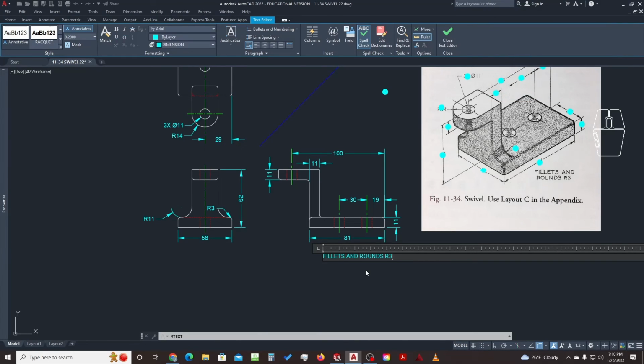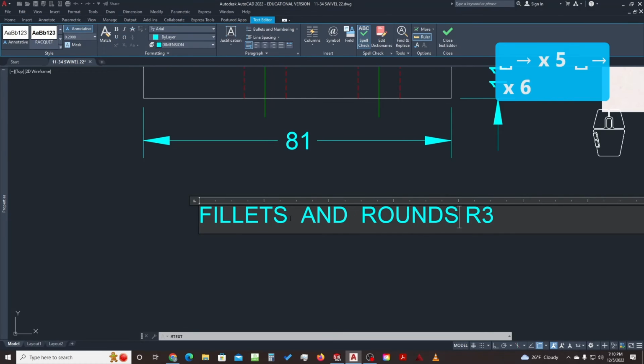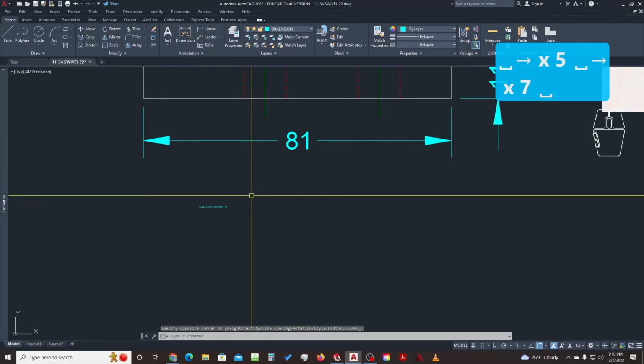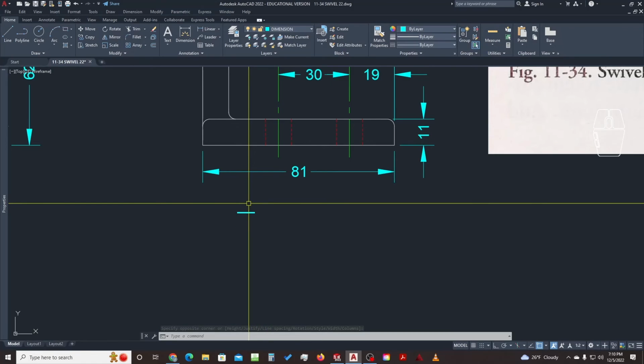And when you are using caps lock, this is not 100% mandatory, but it is very good practice to add a double space between words because it reads so much better. Right now, because it's all capitals, these words kind of run together. Best practice is to just add an extra space when you're in caps, and we're always in caps in CAD. So click out and look at the size of that. That's not good.